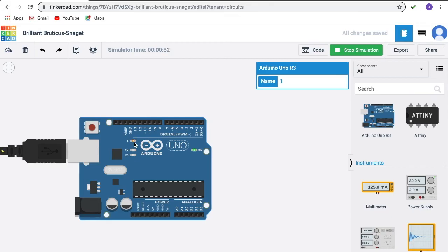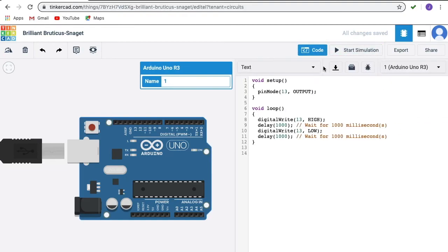So your objective is to change the duty cycle. If you consider this as a square wave, it has a 50% duty cycle. So if I want to change the duty cycle to 75% or 25%, how will you change? Yes, exactly. You have to change it in the code. If I want to change the duty cycle, I have to change the delay time in the program.